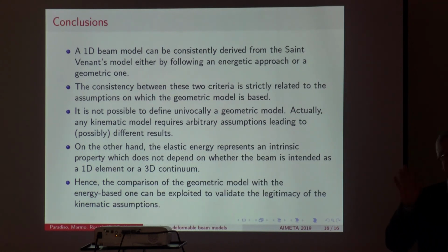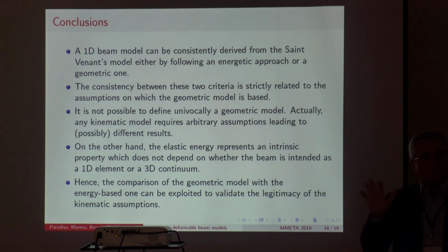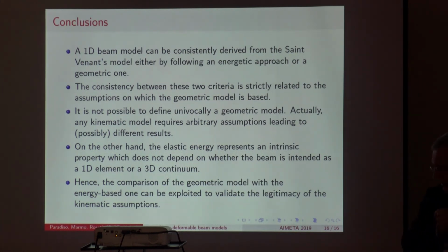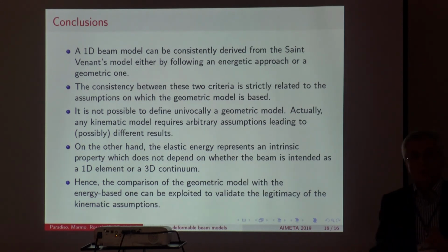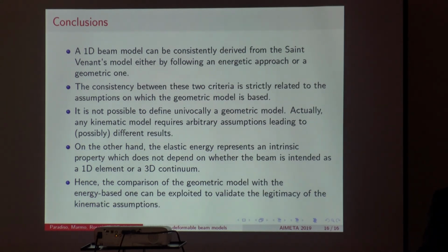You have these two points that govern these two behaviors, and you can do everything. Another source of confusion is, as you well know, that the center of shear depends upon the constitutive properties of the material. The center of twist does not. So it is really a geometric quantity, like the center of gravity.